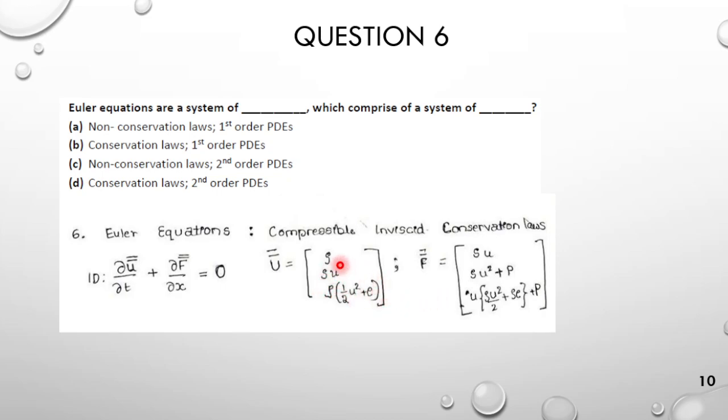I have considered just a 1D domain. In the first equation you have dou rho by dou t also coming into the picture, and then as usual dou by dou x of rho u, which is equal to 0. So it can be applied to compressible flows also, inviscid in nature.